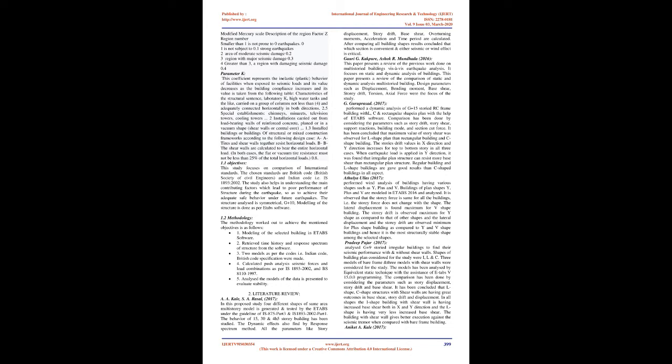1. The height of the structure exceeding 75 m. 2. A difference in the floor height of any floor in the building. 3. A difference in the structural systems and in the building materials used for each of them. 4. A big difference in the shape of the horizontal projection between repeated floors. 5. The non-continuation of one of the structural elements, column or shear wall, throughout the entire building height. 6. A big difference in the distribution of the interior partitions between successive floors.